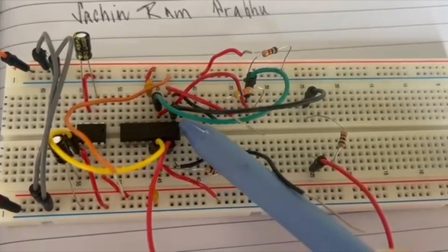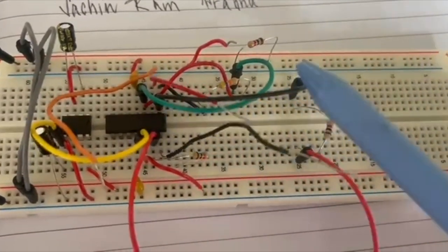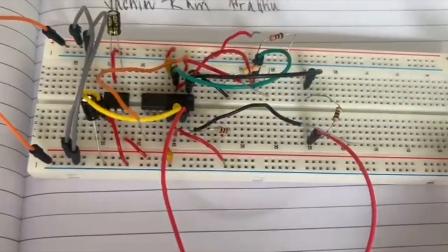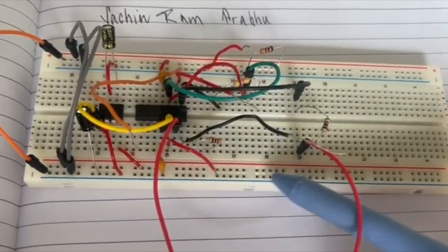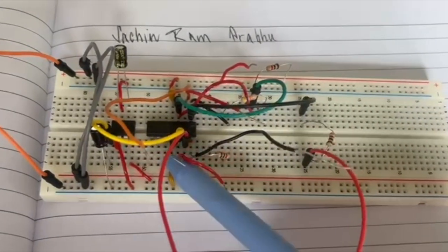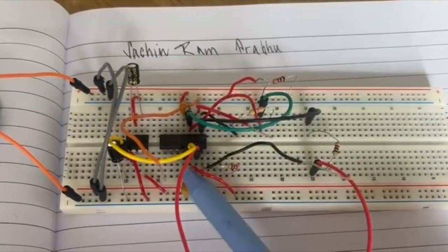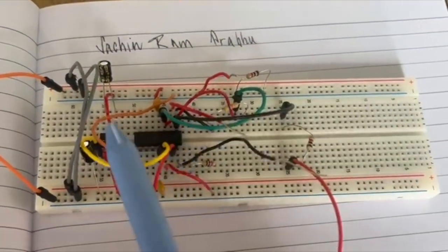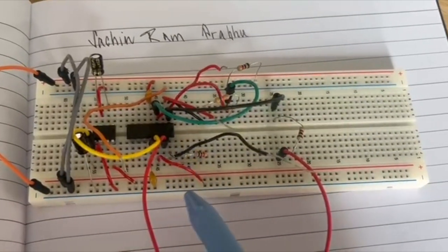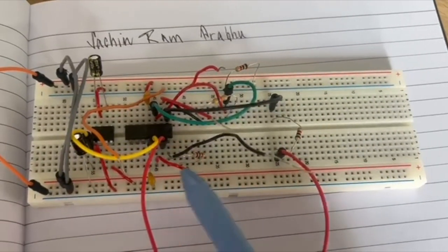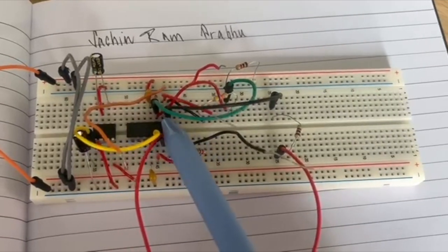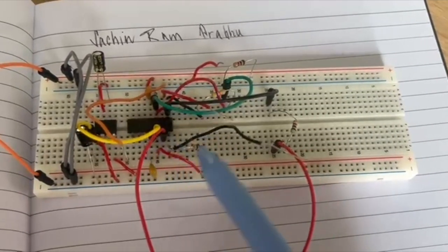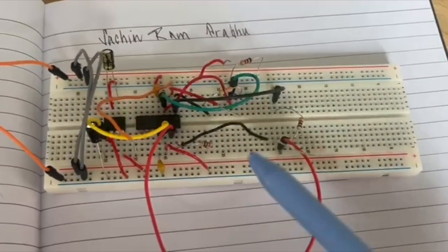Given that the output of this circuit provided was an inverted output, I used the fact that the TL074 comes with 4 operational amplifiers in it to invert that output and get the correct output. This is done by connecting the previous output to the non-inverting input of the second op-amp and attaching it to a resistor and keeping the same connections as before. We can measure the sinusoidal input and the flattened output using the picoscope, and we will see the results of this in the next bit.